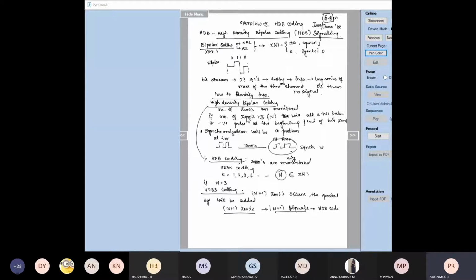And the one coding which we are going to make use of is only the bipolar, not the unipolar or the Manchester or the polar, because polar also will have continuous amplitudes. Unipolar is also on-off signaling. But when you go for bipolar, because three amplitudes we are using, synchronization will be a difficult task. To overcome this, we are using this HDB3 coding.